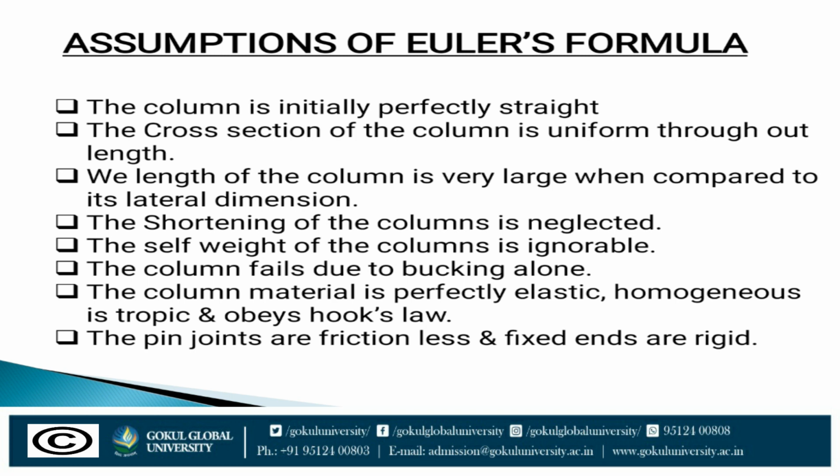The column material is perfectly elastic, homogeneous, isotropic, and obeys Hooke's law. The pin joints are frictionless, and the fixed ends are rigid. These are some assumptions of Euler's formula. We have to follow these assumptions.